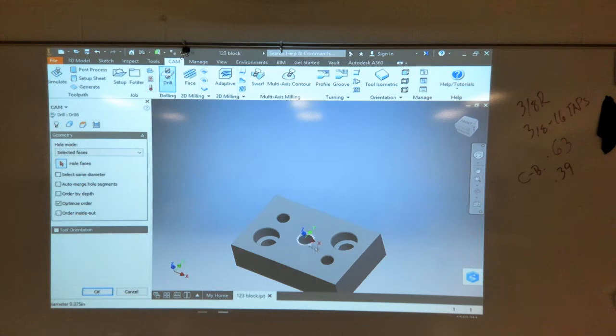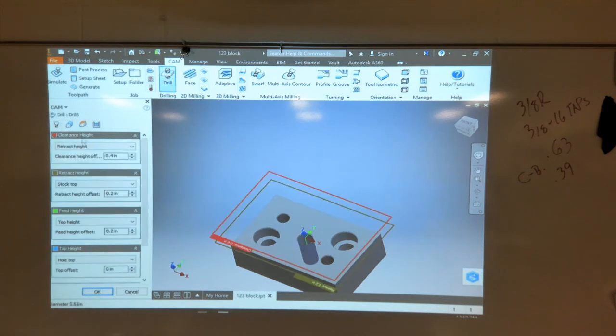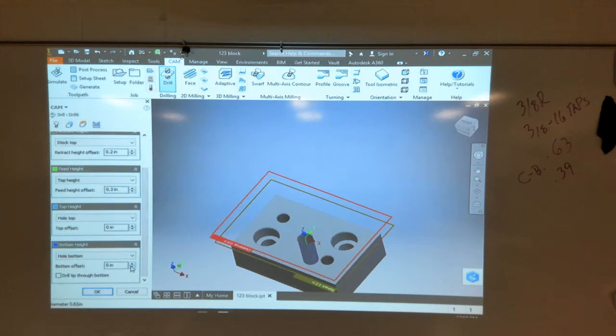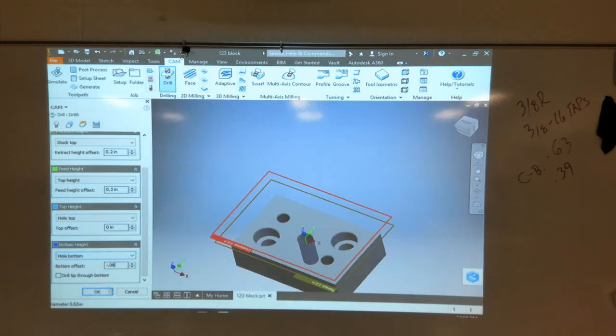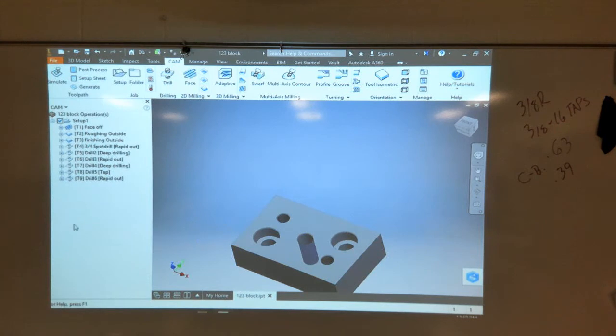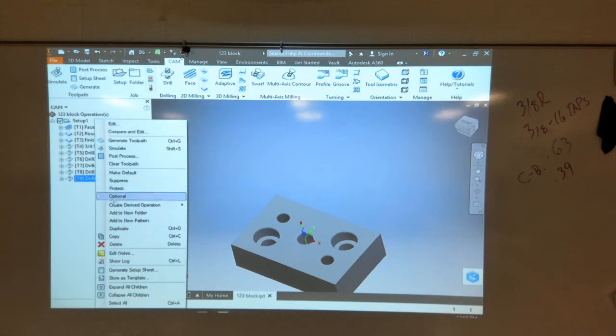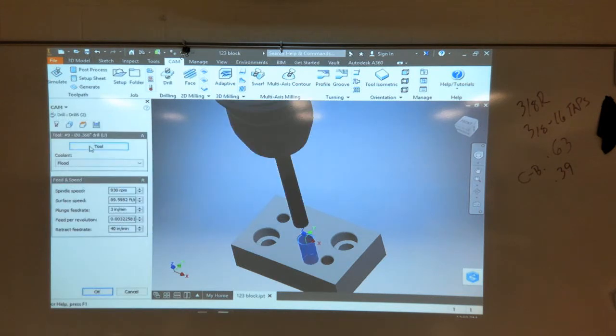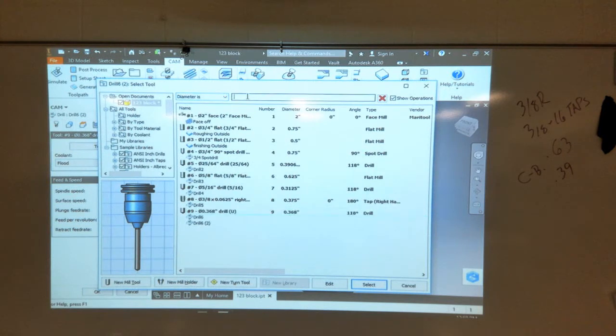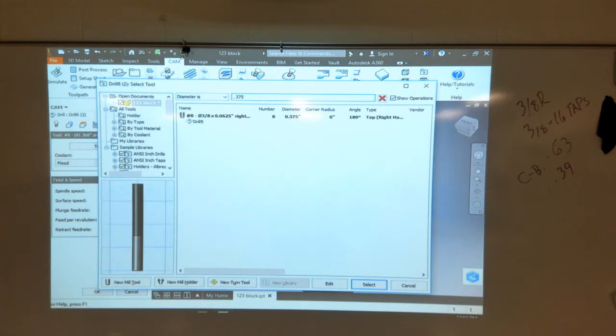Come in, select it, then go down below it because I want to go through it. A lot of this will just be some repetition. Okay, so I've drilled that hole. If I want to, I can just do a copy paste. I can duplicate, go in here, change this tool to a 375, and let's see if we can find it as a reamer.